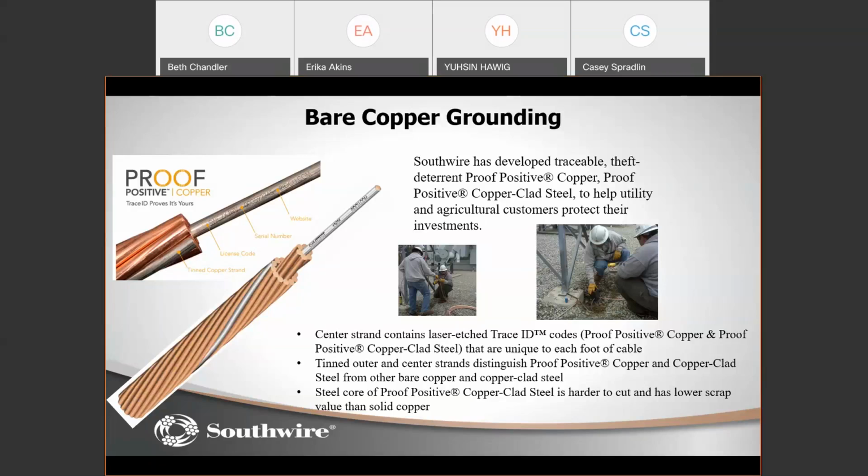So if you are concerned with high humidity exposure, I would say high density polyethylene or cross-linked polyethylene, which is, again, thermoset. The moisture vapor transmission rate for HDPE or XLPE will be much lower than that of thermoplastic linear low density polyethylene.